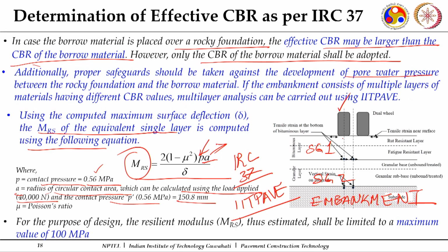With this, through the IITPAVE software, you work out the deflection, and using that deflection value, the contact pressure and the contact area, you get the value of your resilient modulus. So this combination you can work out directly to get your resilient modulus for this particular combination of different layers.